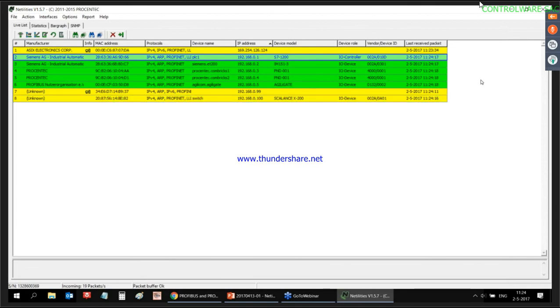You just need to specify manually which side of the communication you want to analyze, because you are connected to one of the two mirror ports. So you are usually connected to one of the two PLCs, and you specify that over there. And also the other question from you, Nikolaus, is about the S7 communication. No, it's not possible to use Profinet to analyze the S7 communication deeply.